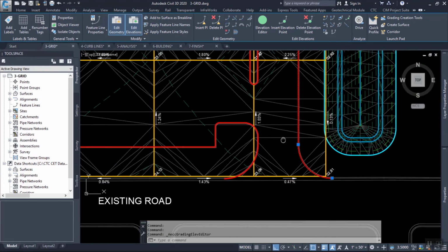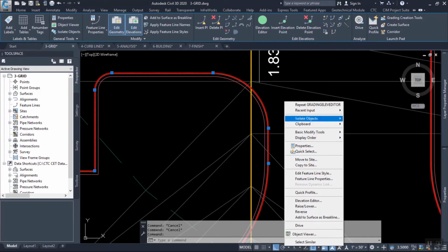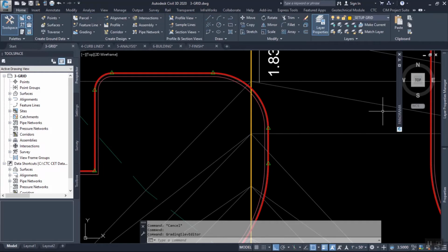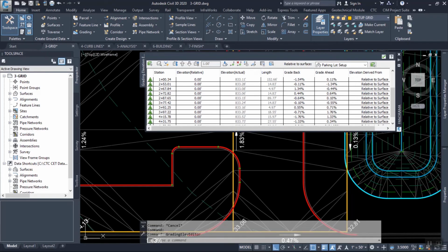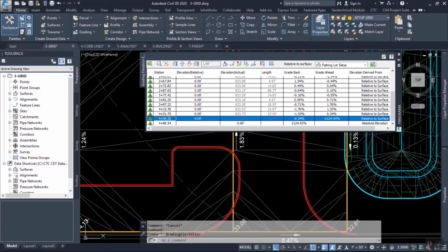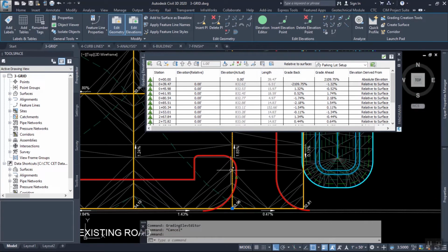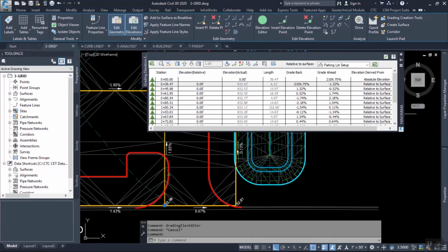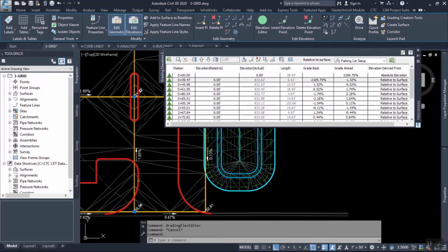Let's do a little experiment. Okay, this feature line, this point is that point right there, right? Its elevation is 822.62. Okay, when I take this grid feature line, it'll affect those, and I'll just do it one so you can see it.